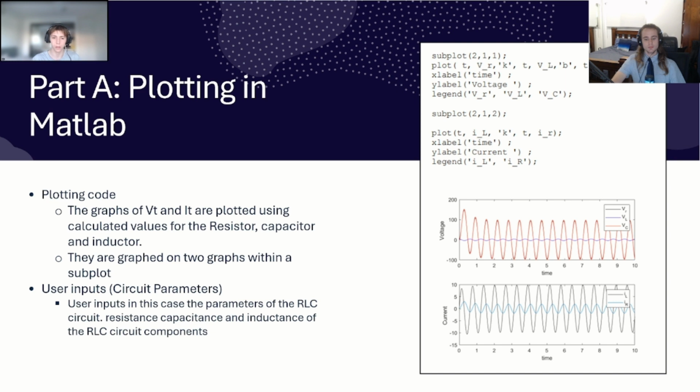Another plot was made to show the frequency response by measuring the current across the resistor at varying frequencies, and then finding the ratio of the input voltage to the output voltage. These values were then entered into a list for X and Y, and then using the semilog function were plotted onto a graph.